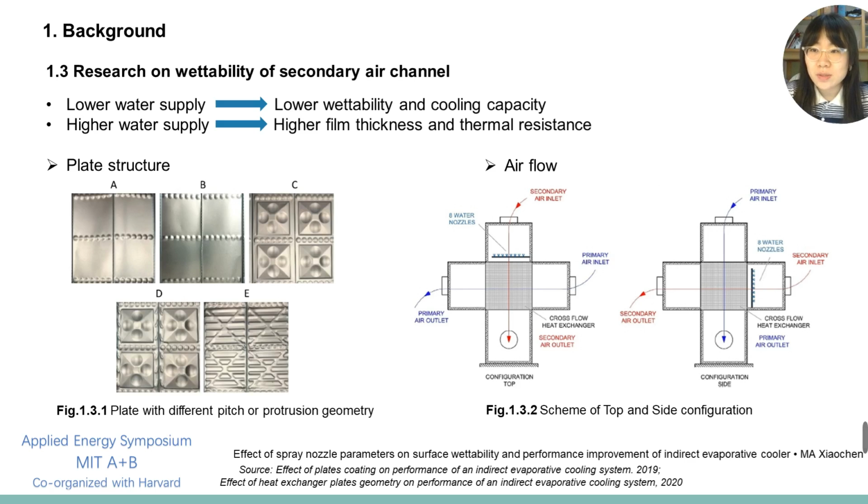And for the wettability, if the water supply is lower, it will lead to lower wettability and cooling capacity. Well, if the water supply is higher, it will lead to higher film thickness and thermal resistance. So it's important for us to find the balanced value to achieve the best wettability. Because of its importance, some studies have been carried out recently,